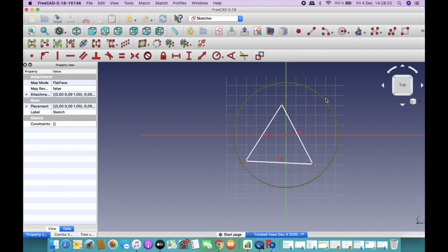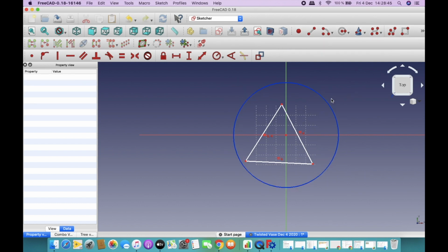First let me select this, and then I go to this option over here which toggles the toolbar or selected geometry to or from construction mode. So if I click on this, then the circle I drew becomes a construction line. Okay. Now what I'm going to do is enforce a constraint where I will say